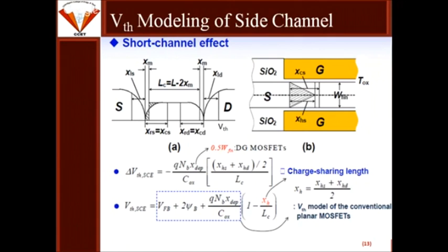So if we talk about FinFET modeling and the earlier MOSFET modeling, the basic thing is that the equations of the current voltage relation and everything are almost the same. The only thing that is going to change is the VTH, because if we look at the curve, that curve is almost the same, except that it has a reduced off current. So off current is reduced, and you can think of the threshold voltage as changed. Various parameters are indicated in this figure with the 3D view of this FinFET.